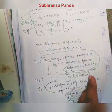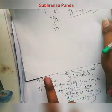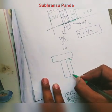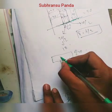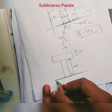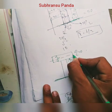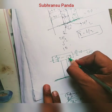Okay, next thing is important. This is y2. What will be y2? This is given 100, this is 20. So y2 will be what? We will be calculating distance from this axis. For this section the height is 20, so the centroid will be at 20 divided by 2, so it will be here, 10.